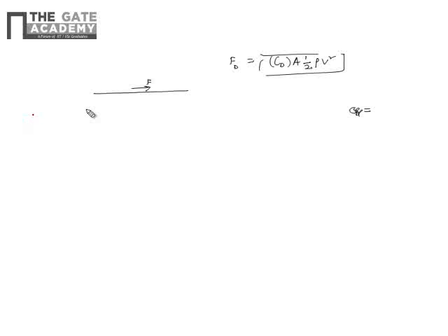First, there are two important things which you should know. One is your local friction coefficient, and the other is your boundary layer thickness. The boundary layer thickness you have already defined. The second is the local friction coefficient. Let's first define these two terms. Boundary layer thickness I have already defined: it's the normal distance from the plate where your velocity reaches the free stream velocity.